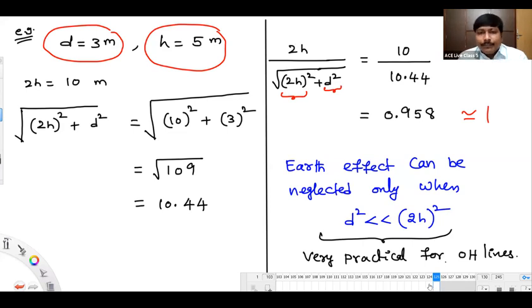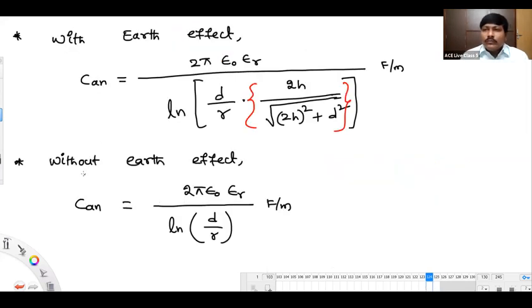I want to have a comparison between these two. Okay, almost same. That's okay. Almost same, but still, among these two numbers, which number looks to be more? Even if you consider the insulator string length and all, minimum ground clearance has to be maintained, no, Vijay? Always the ground clearance is measured from conductor to ground, not between tower and ground, not between the cross arm and ground. We have to measure the clearance from conductor to ground.